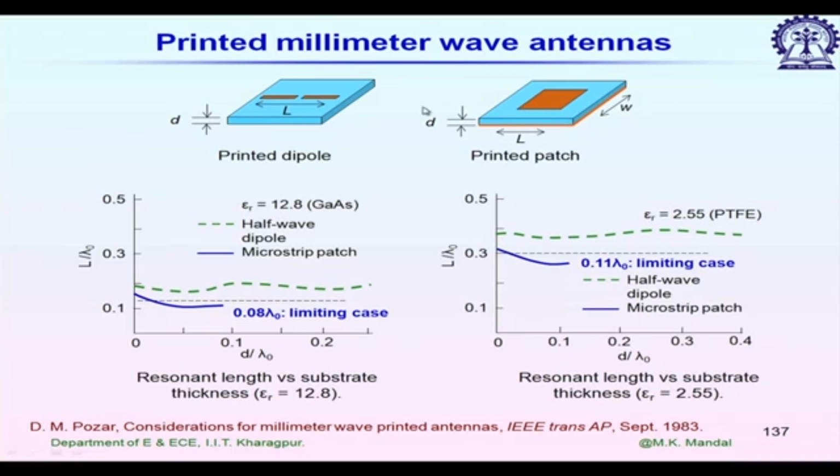If you look at this structure, surface wave for left hand side and right hand side will have different characteristics. Why? In left hand side, we do not have any ground plane, simply the dipole printed on a laminate, and right hand side we have rectangular patch on a dielectric slab backed by ground plane. So, looking back to surface wave properties, for the left hand side case we have to consider simply a dielectric slab, and for the right hand side a dielectric slab backed by ground plane.